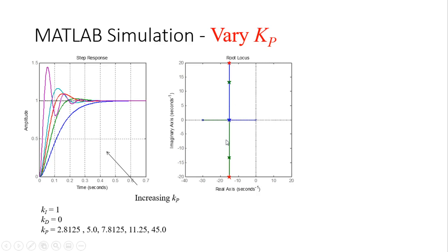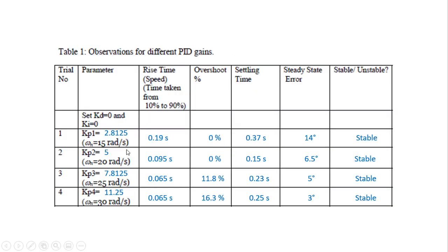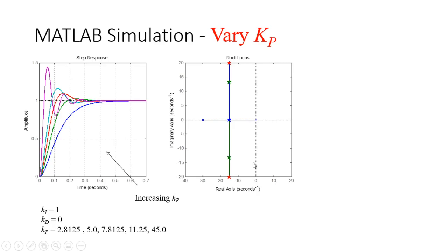And the roots will split, and then we'll have the same settling time. Initially, your settling time could change, right? It got reduced. Then what happened? Once it's underdamped, it doesn't change anymore. Settling time will be the same. So root locus can explain why the response changes in a certain way.